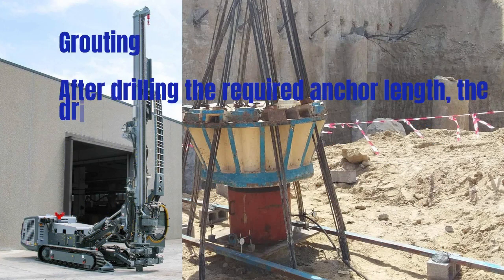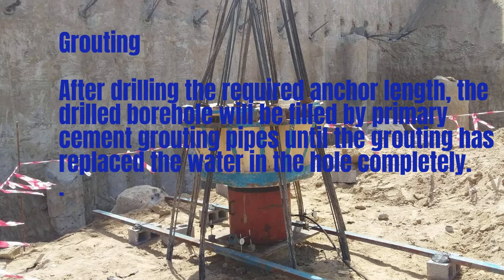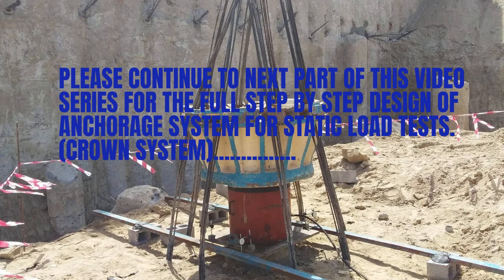Grouting: after drilling the required anchor length, the drilled borehole will be filled with primary cement grout through pipes until the grout completely replaces the water in the hole. These are some of the points you should know. Now I will go directly to the design part.